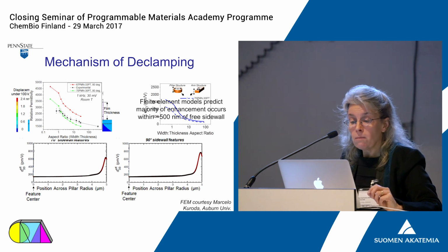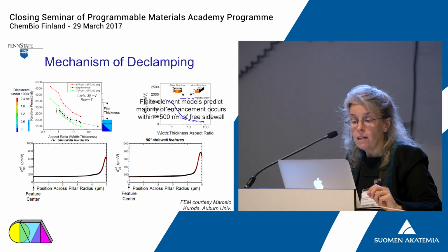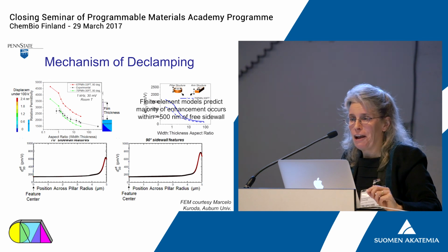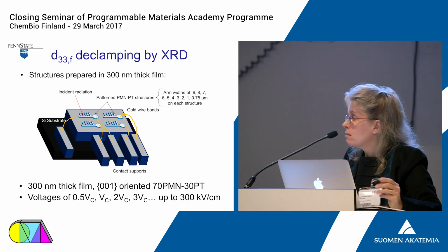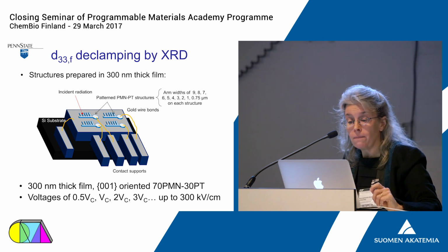The finite element models say that you should laterally declamp about the outer half micron of the device. And so it doesn't matter how big you make that device, you're going to declamp the outer half micron. And so we then tried to make devices where we could characterize that.